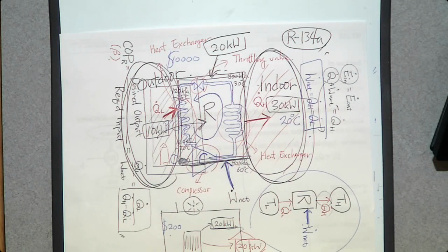So if you buy a heat pump here, it's not just a heat pump. It has an auxiliary heater embedded. So the system has two options: run the heat pump or run the traditional heater. The way it works is that you set a threshold temperature. Let's say the threshold temperature is 5 degrees Celsius.